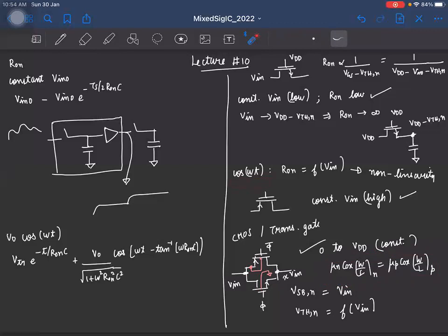If you are dealing with a constant input signal, that is a held signal like this, a CMOS gate works perfectly. So for successive stages like this, where we are sampling a held input which is constant, we can use a CMOS gate, a CMOS switch, and that will work perfectly in most cases.